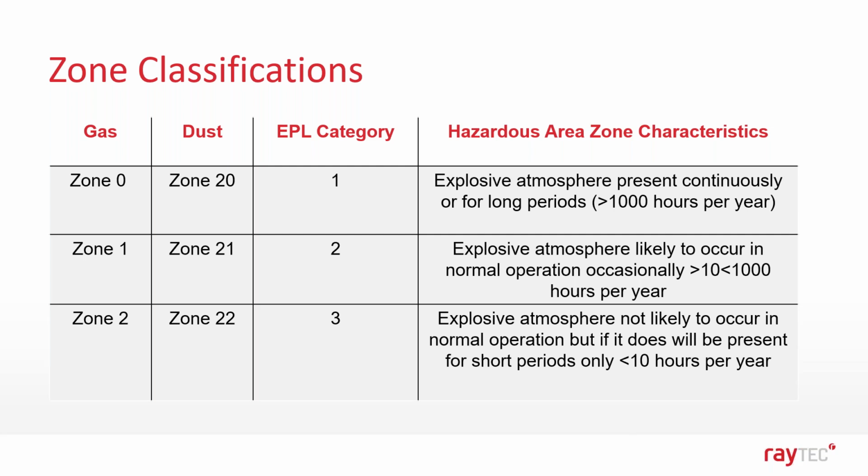In these situations, the explosive atmosphere is not likely to occur in normal operation, but if it does, it will only be present for a short period of time. So generally less than 10 hours per year.